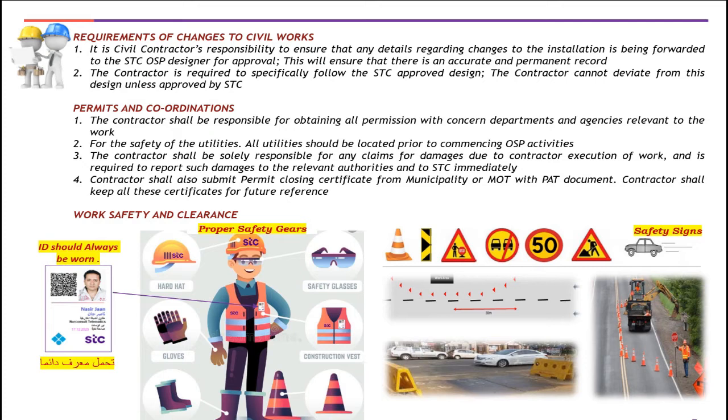All debris shall be removed from the work site to the designated area specified by concerned authorities. The site shall be restored to the condition in which it was found, always. A contractor shall post his name, emergency contact number, address, and municipality permit on a board installed prominently near the work site.